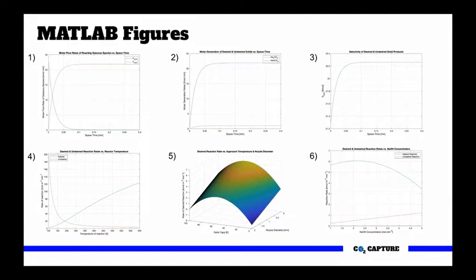On this slide is a collection of figures created from the MATLAB code and represents the trend which led to the final reactor specifications and operating parameters. Figure 1 shows that as the molar flow rate of carbon dioxide levels drop with spacetime, the molar flow rate of water vapor increases before reaching a plateau around 0.15 minutes. Because water vapor is the only gaseous product of the desired reaction, it becomes a major component of the exiting gas stream.